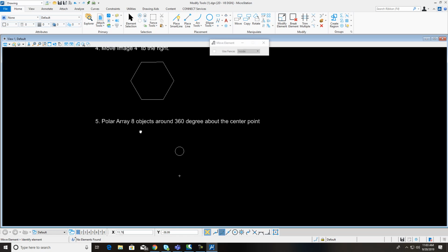Polar array this object 8 times for 360 degrees. Up here are your array buttons, and just change it to polar. Alright, I want 8 copies. Go ahead and fill out this first. 360 degrees is what I want.